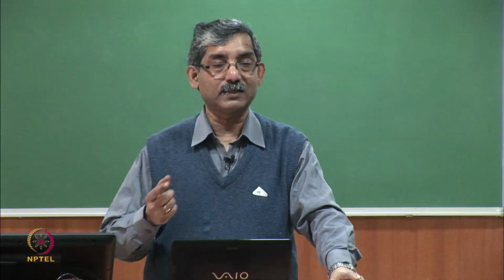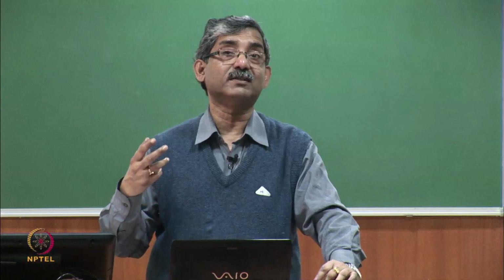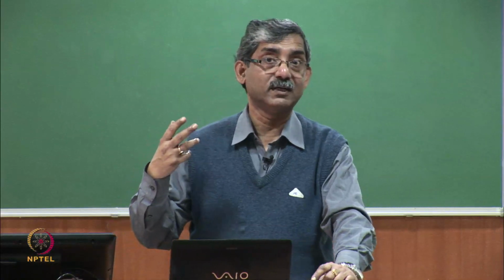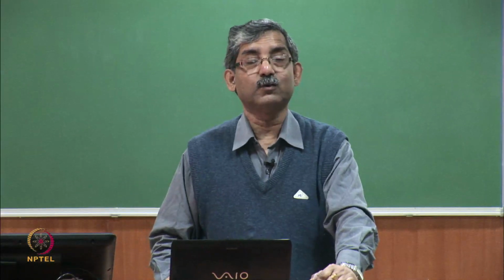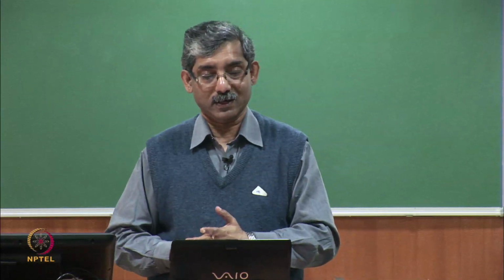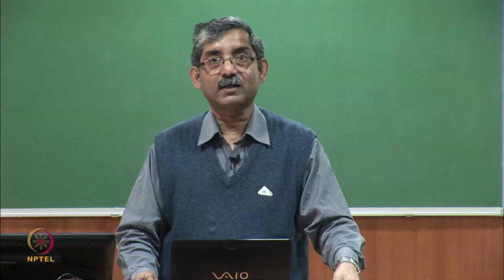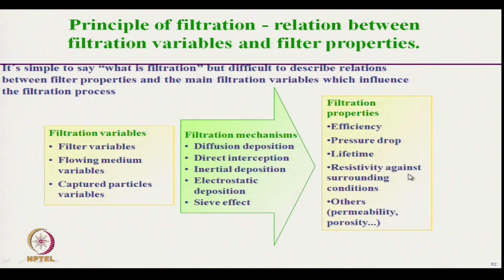If the filter is very expensive or changing it is difficult, we must consider a higher life. We must understand the resistivity against the surrounding conditions, if the temperature is very high or stress is very high. Accordingly, we must select the filter fabric.